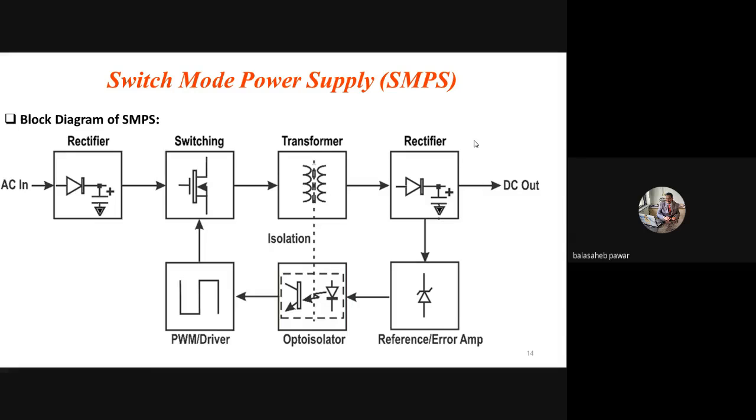So basically how SMPS works, or what is the basic functioning, or how we can achieve somewhat lower DC voltage converted from very high AC supply without any step down transformer, all that I already explained yesterday, right? We took that example: if 230 volt AC is directly rectified, the obtained DC comes as 207 volts.